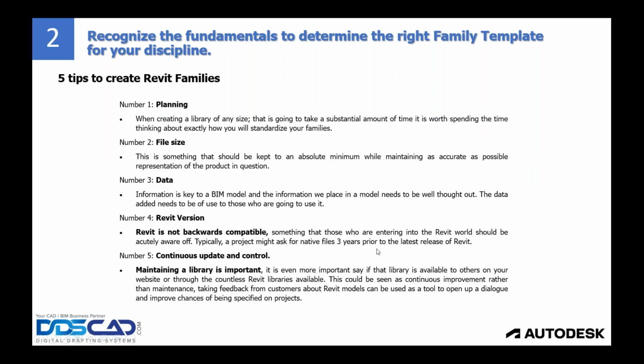I'm not going to go through all of these lists, but I actually find that in order to create a good loadable family or component, I need to go through stages in a very organized way in order to be successful. Revit is a very organizational program. So if we are organized as well, then we're going to have success in our dealings with Revit. So planning the family, the file size, the data, even the version that we're going to use for creating the families is important to keep in mind.